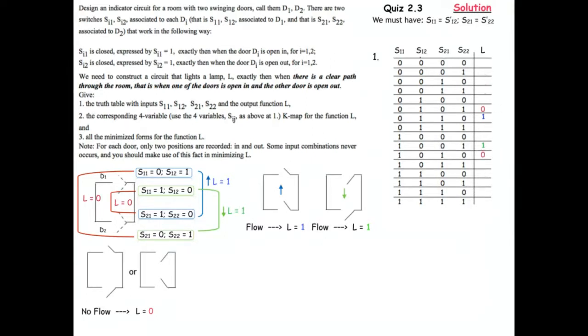Right? If you misinterpreted it, then you would have the opposite. You would have 1, 0, 0, 1. I have 0, 1, 1, 0. Doesn't matter, right? What matters is that the rest of them are disallowed here, so they're the don't care conditions, right? All of the other possibilities of the switches when they're not the pairs are not complements of each other, right? Or we'll say that they don't happen, don't care, right? Never occur. Right? All of those are Ds.